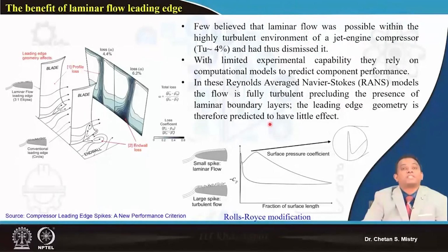So in order to study what is happening on my blade surface, we will be selecting a larger chord cascade. When we have a larger chord cascade, we can capture the minute details of what is happening on my suction surface, and in the same way on my pressure surface. The data we capture using a cascade tunnel with recent measurement techniques, maybe PIV, or hot wire anemometry with flow visualization, gives us a whole lot of data. That data can be used for validation and for the development of new turbulence models that we use for our CFD analysis.